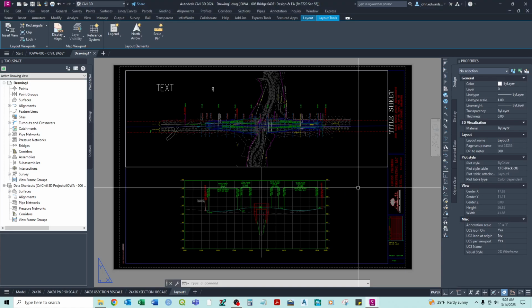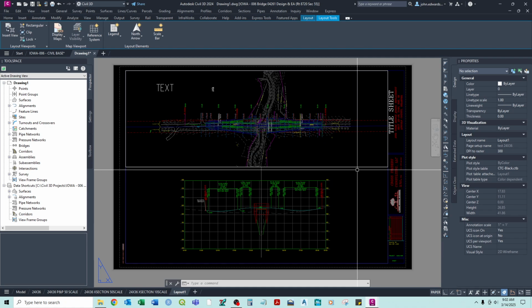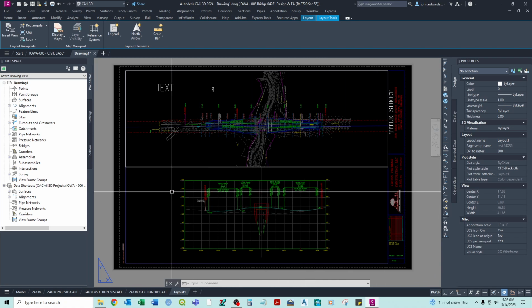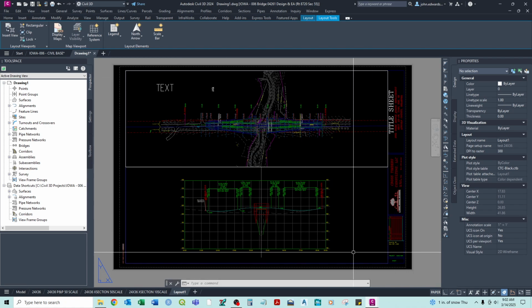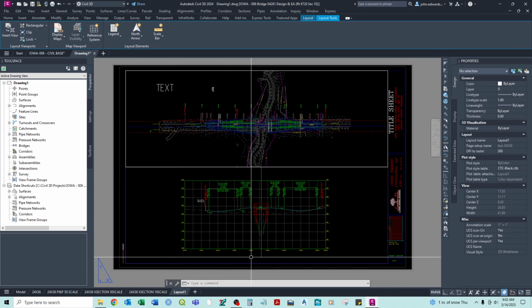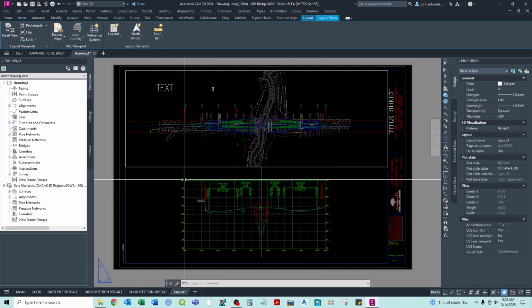Okay, this video will continue discussing sheet creation and layout, and just a few more ways to manipulate those things and ways to label some of the features in working with viewports. So in the last one, we created this PNP sheet from scratch, based on a new layout that we created. We resized it and added in these viewports.